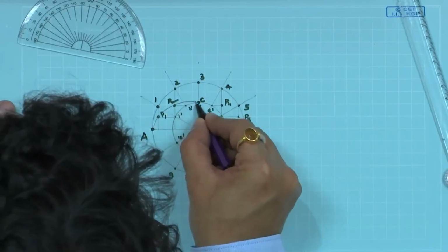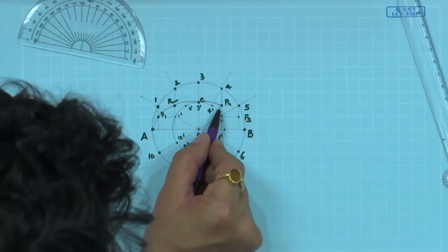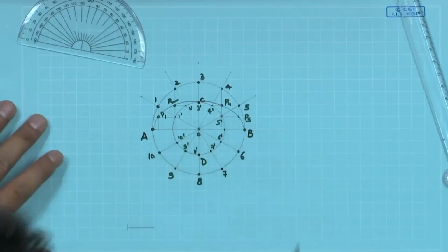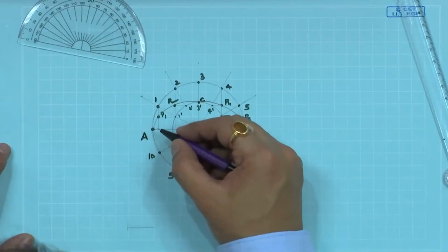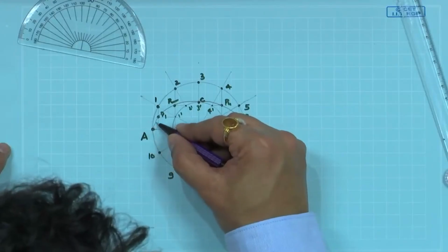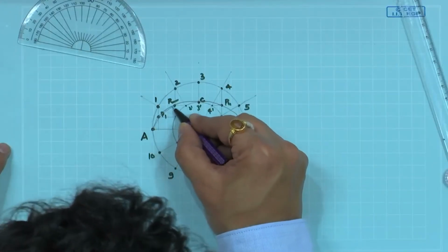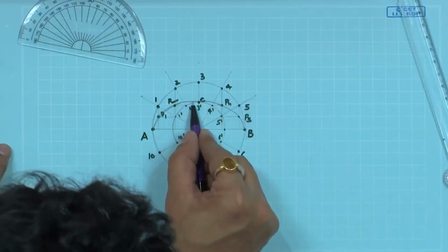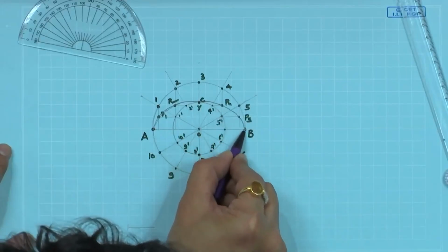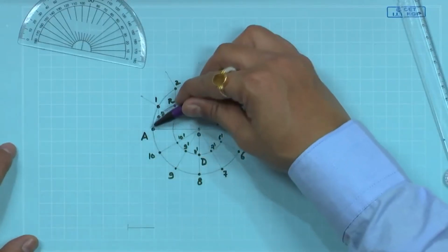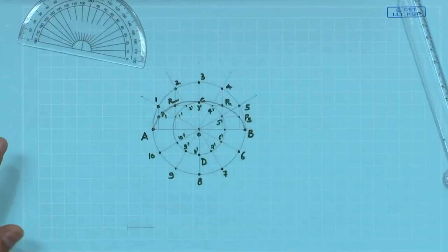Now, draw a freehand sketch which is passing through A, P2, P3, P4, P5 and B. If we have French curves, one can smoothly construct a nice line which is passing through those points. Similarly, one will be in a position to construct the bottom lines also.